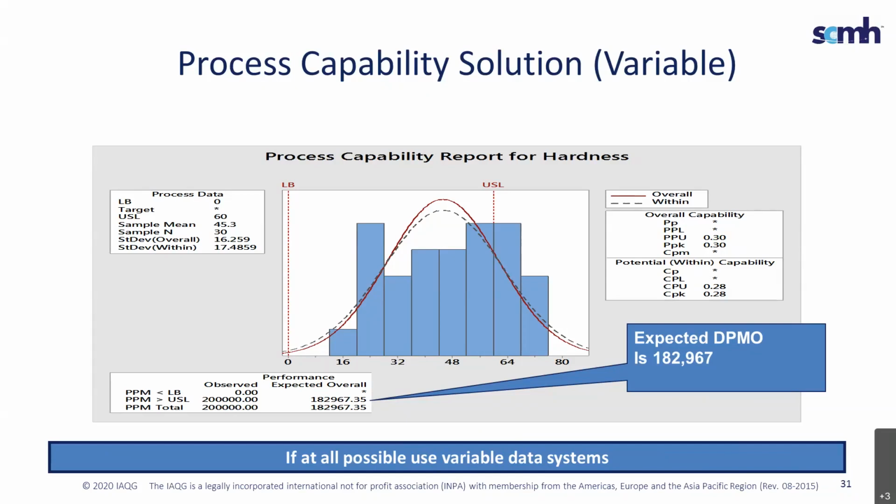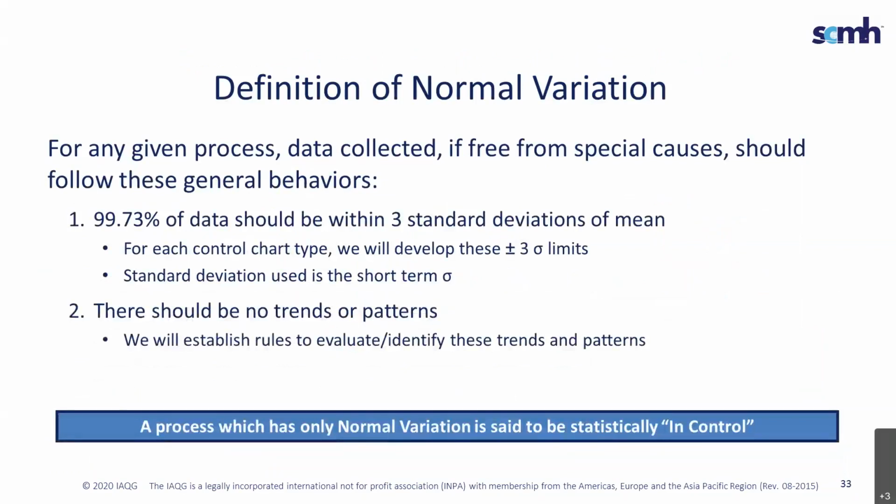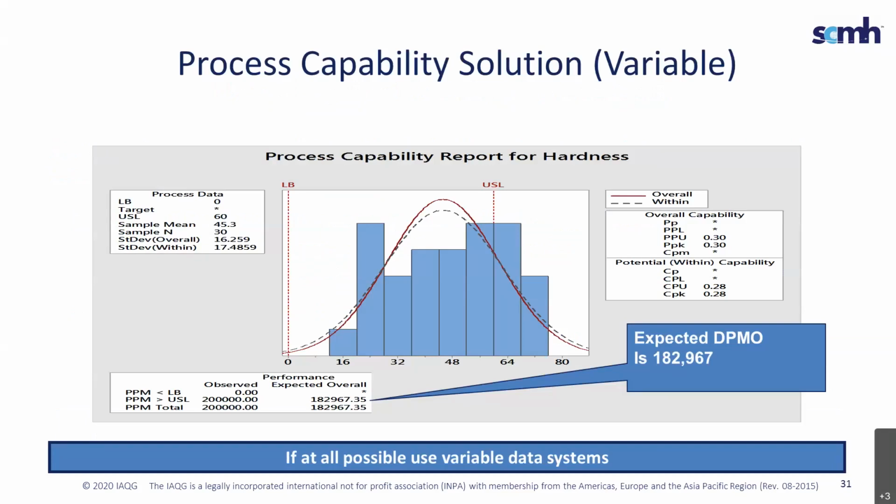And this one's for slides 33 and 34, before you go back to slide 70. What if the process can't be centered between USL and LSL? Example, we measure a contaminant with limits 0 to 30 mg/L. How should our process be targeted in this situation? So it's very similar to the Rockwell hardness. I'll use that as an example. You're probably not going to be able to center this process, or maybe you can, but you also have a lower bound.